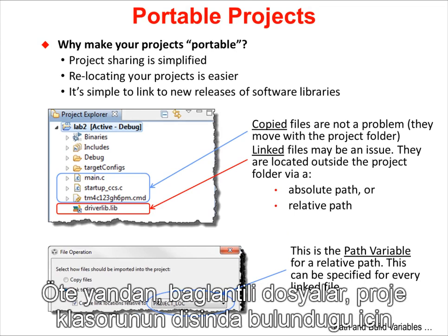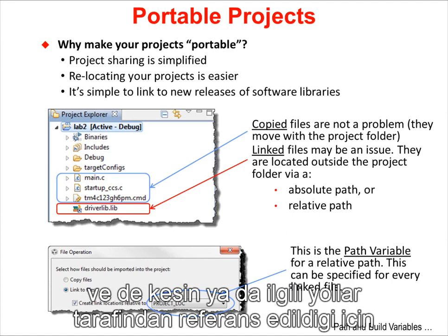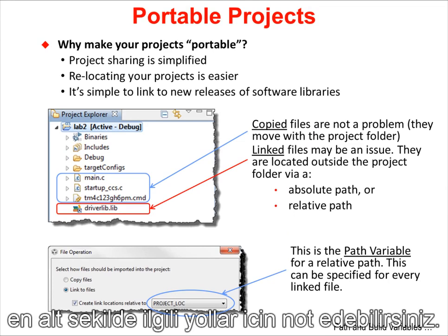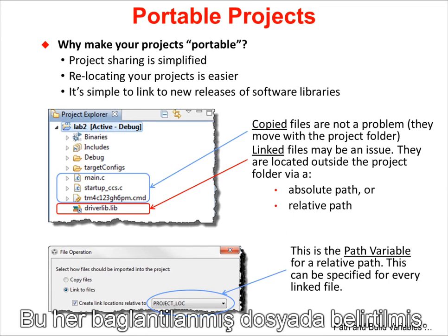Linked files, on the other hand, may be an issue since they are located outside the project folder and are referenced by either an absolute or relative path. Note the path variable in the bottom figure for the relative paths. This is specified for every linked file.